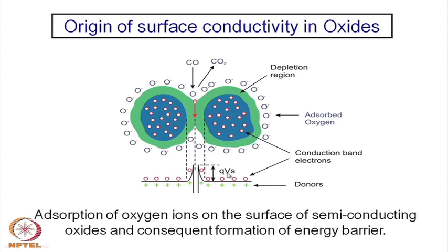Okay. So, this height is actually this expression. The primary reason for the depletion zone is adsorption, which is the inherent characteristic of all semiconducting oxides in the presence of enough oxygen. So, this is the characteristic: a depletion zone and adsorbed oxygen ions.